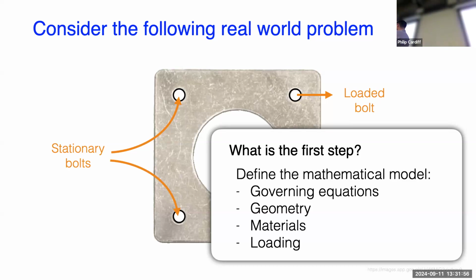So applied to the governing equations, you'll say, well, sometimes there's a 10-degree variation in the temperature in the lab. I don't know if that's important for affecting the yield stress. Should I include that or not? So KISS says don't include it, just do the analysis without it, check if the model is useful or not, then go back if you think that's a critical factor.